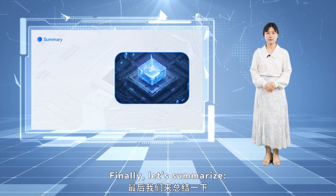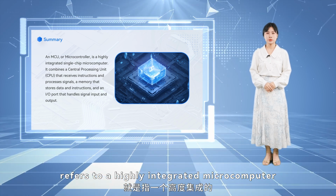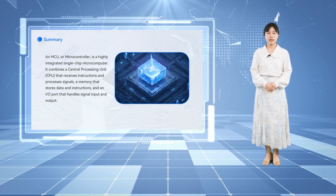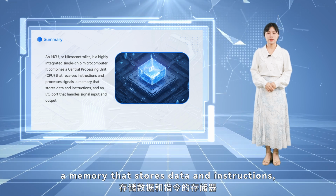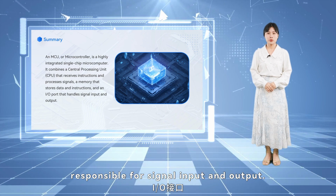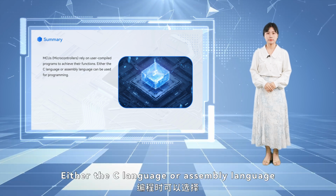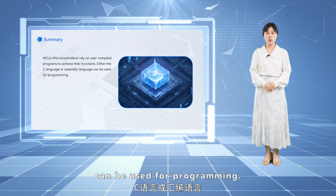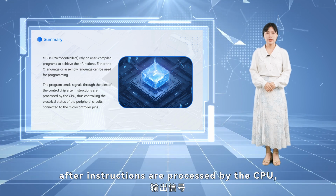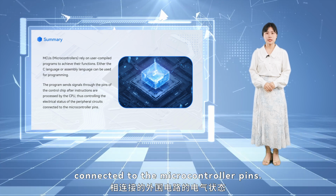Finally, let's summarize. A microcontroller unit, MCU, refers to a highly integrated microcomputer on a single integrated circuit. It consolidates a central processing unit, CPU, that receives instructions and processes signals, a memory that stores data and instructions, and an I/O port responsible for signal input and output. MCUs rely on user-compiled programs to achieve their functions. Either the C language or assembly language can be used for programming. The program sends signals through the pins of the control chip after instructions are processed by the CPU, thus controlling the electrical status of the peripheral circuits connected to the microcontroller pins.